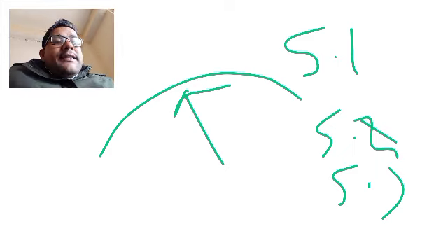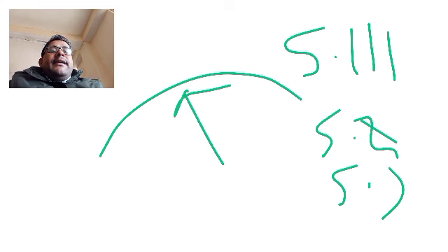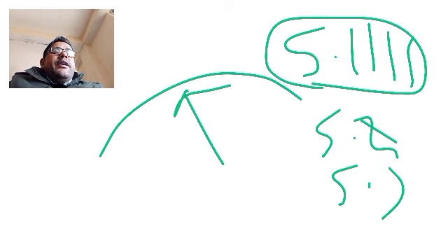But if we increase this value by 1.12, this analog instrument is not responding to that value, because the scale is not able to detect and display these small changes. That's why its accuracy is limited. But in a digital instrument, this can be detected. So accuracy is limited by scale resolution. This is the point we are discussing.